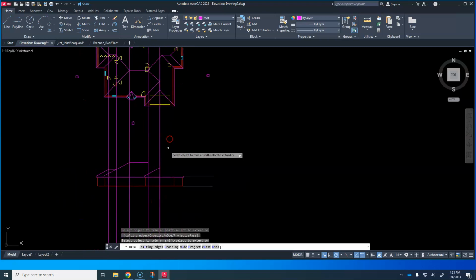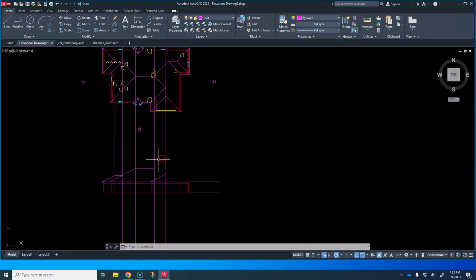So what else am I seeing? I drew this one. I've got this right here. The valley isn't going to show up because it's right behind that line. But what I do need to see is this line coming down from that main ridge line, at that same angle. It looks like it comes down and meets this line right here, just like this one went up to meet that line. So it's real easy to draw that one. Just find that intersection and draw it just like that.